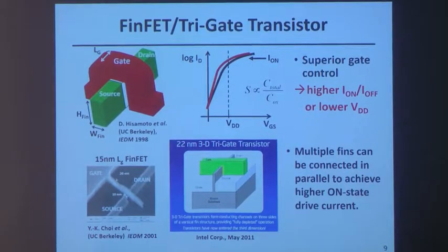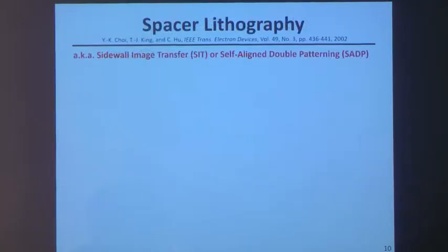And so of course, circuit designers would like to have some wide channel devices as well as narrow channel devices in different parts of the circuit. That would mean taller fins somewhere and shorter fins elsewhere, but that's not really easily manufacturable. So the industry went to using multiple fins in parallel to increase the drive strength of a FinFET transistor. So that's how it's done.